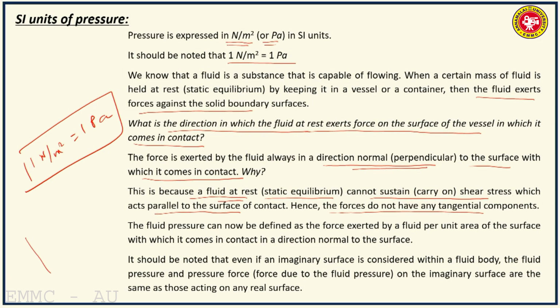Say for example, I have a container in which a liquid is stored with a free surface. The fluid is at rest, it is in static equilibrium, it is not moving, it is not subject to any shear stress, that is, parallel to the surface. So therefore there will not be any deformation in the horizontal direction. So there is no force acting in this direction. There is force acting only in the vertical direction, that is normal to the surface.